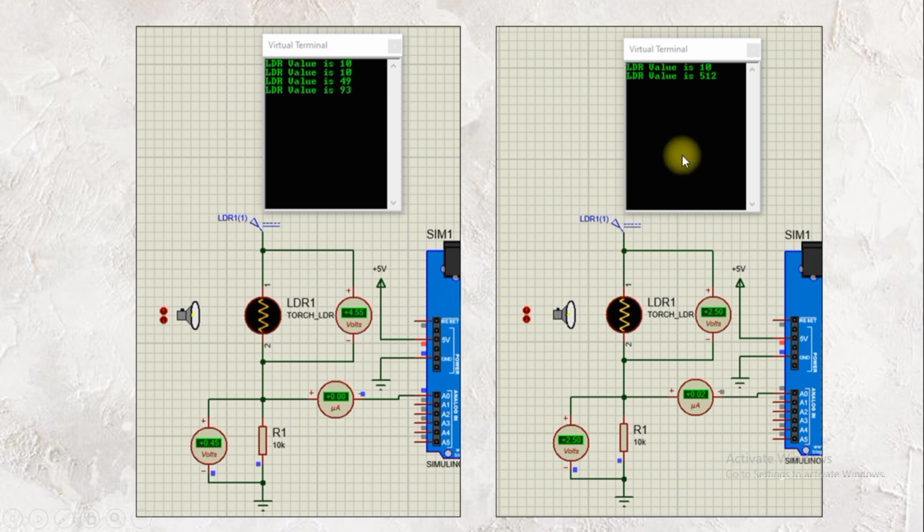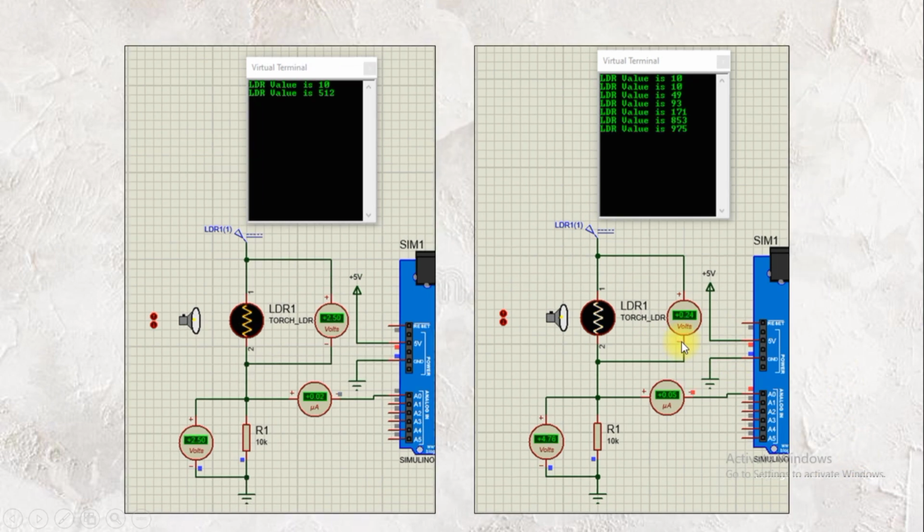And then for the last value, which is 512, we know that it is more than 100, so this confirms that our smart street lighting will not be turned on because our first requirement, which is LDR should be less than 100, is not fulfilled. Also the same goes with the value of 975. Increasing the LDR value will affect the performance of our smart street lighting.